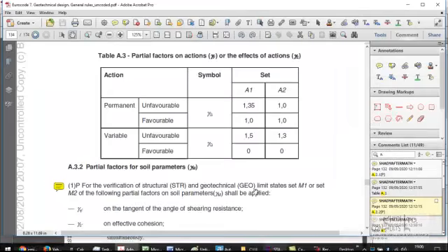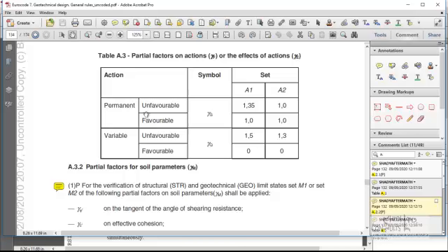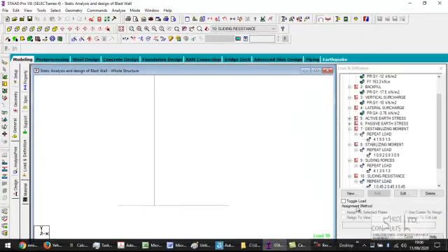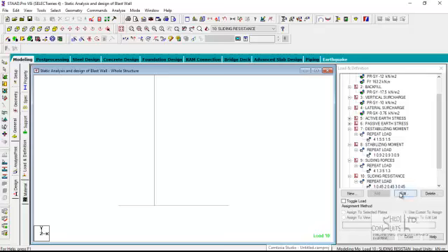So we look at the partial factor of safety that we had used for the unfavorable load case, which is the dead loads now: the backfill, the self-weight of the structure, and then the vertical surcharge. Those are the loads that are resisting the sliding, because when the forces are causing sliding, the sliding resistance is a function of the coefficient of friction between the foundation base and the soil, times the normal reaction.